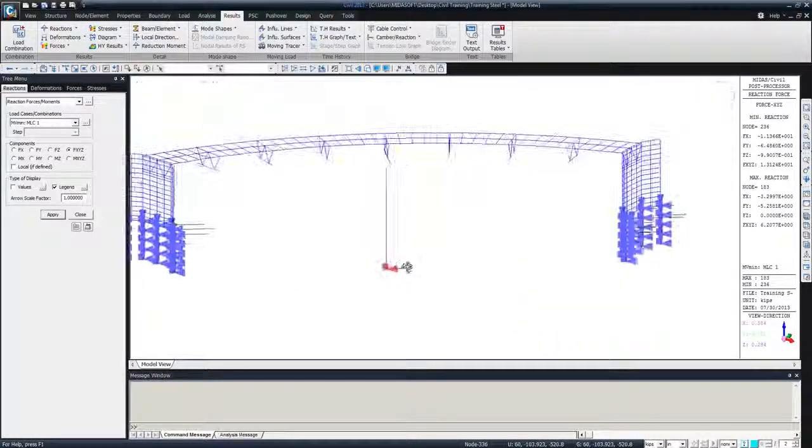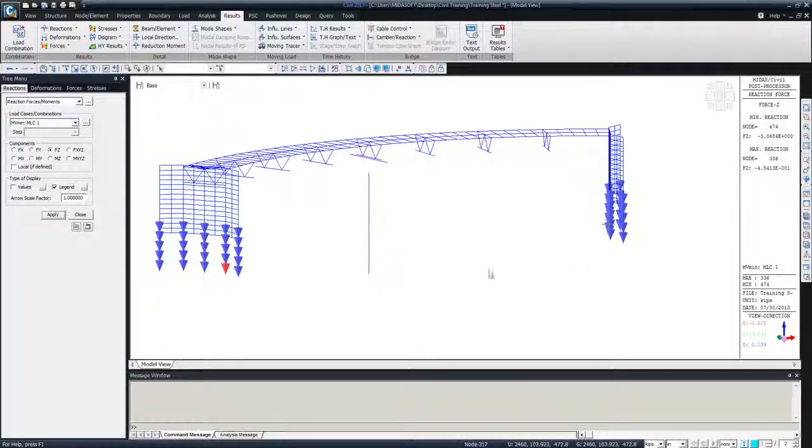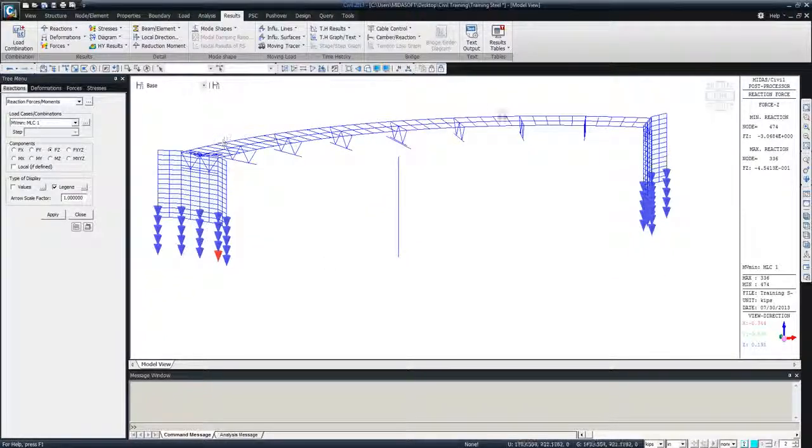Just know that because you see here we had these moments, the supports. Just keep in mind these results are under the moving load, because sometimes engineers make a mistake. They are checking, for example, in the vertical direction, these reactions, and then say the results are not matching with the total self weight that I have. Just consider that these reactions under the moving loads are not happening at the same time. Again, I'm just repeating this one.